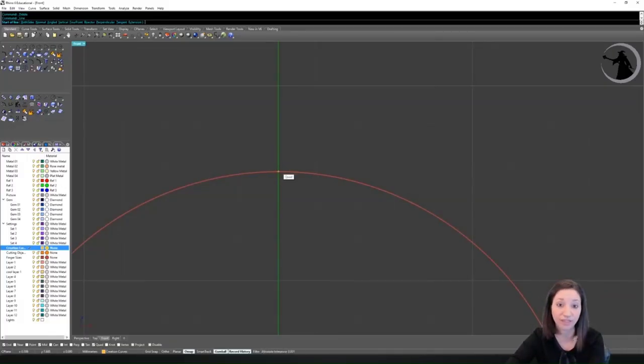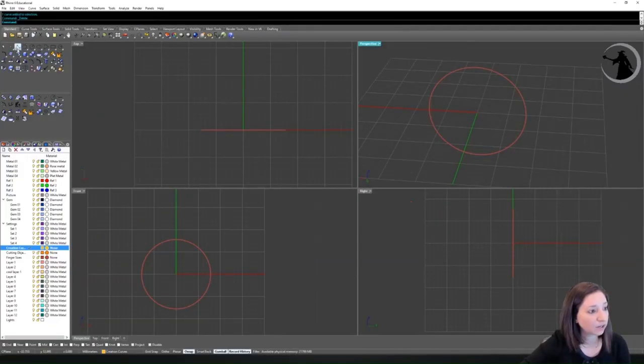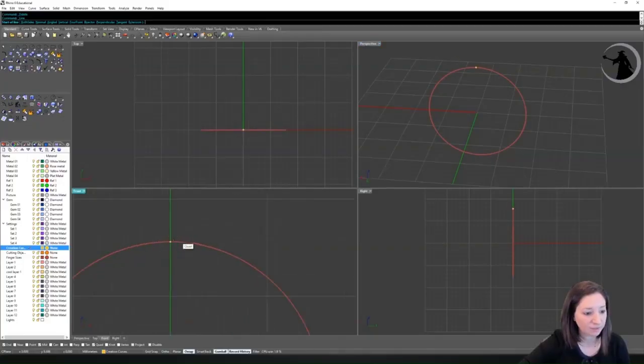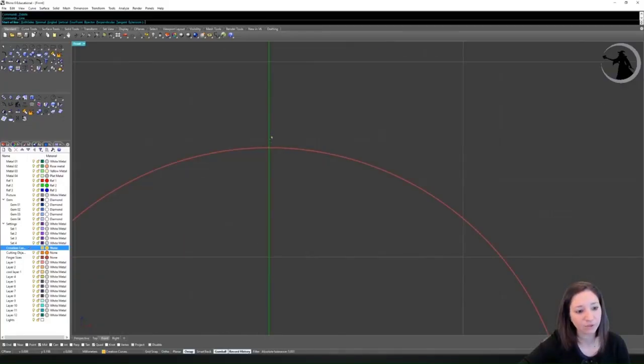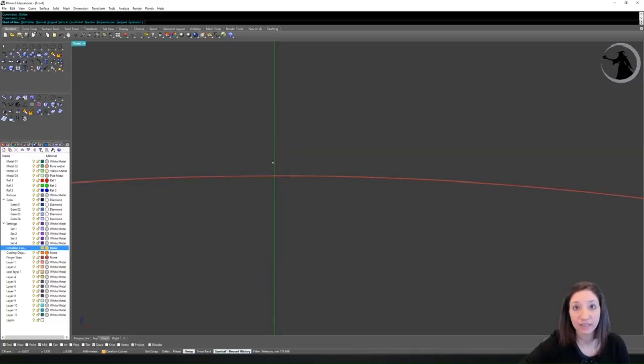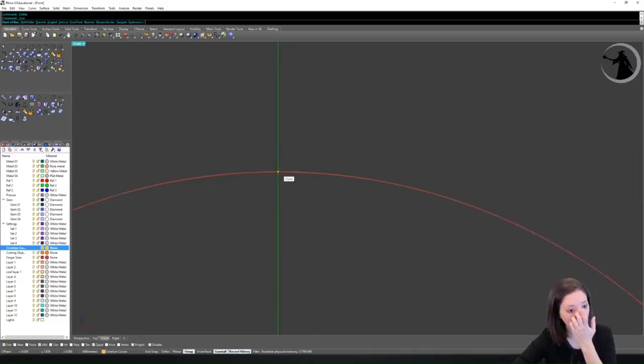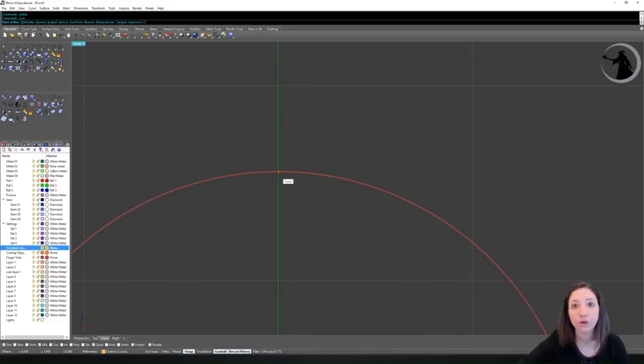So when you draw things, they're actually touching mathematically as opposed to you trying to go in and do it without these. When I start my single line, notice that if I bring my mouse close to this circle, it's actually pulling the center of my object towards the curve. And then the little word, this one is quad, if you can't see it, is popping up.